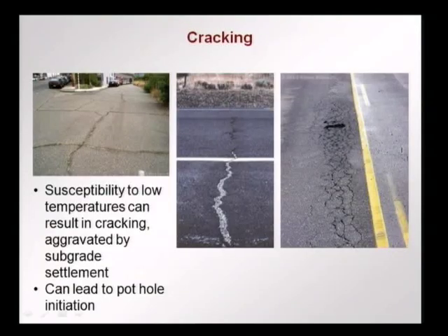On the other hand, we can have cracking occurring when the viscosity is too high, so that there is not enough flexibility in the pavement to adapt to the stresses that cause cracking. This occurs very much when the temperatures are low, and it can be made worse when we have subgrade settlement.